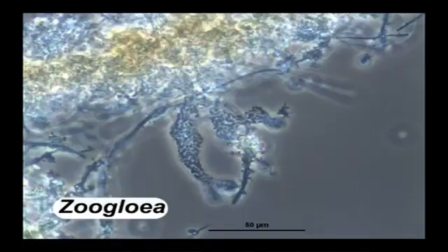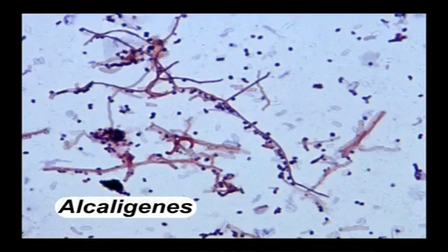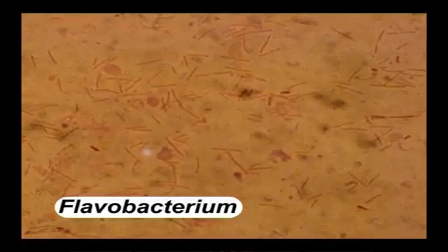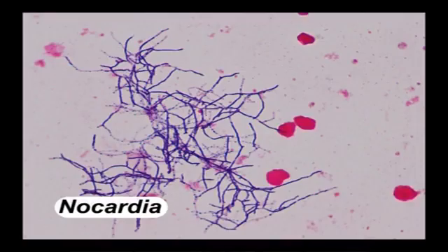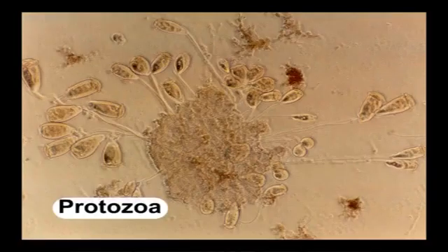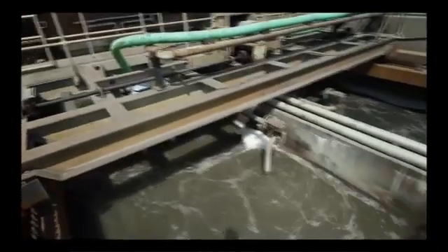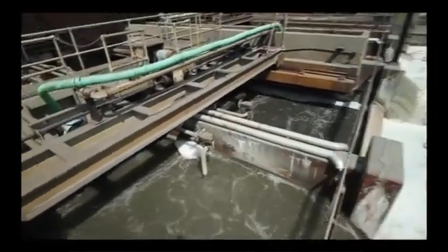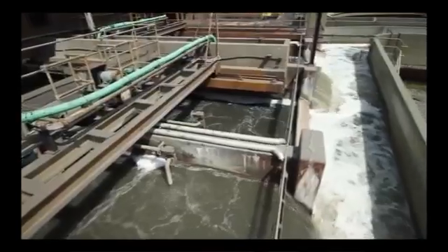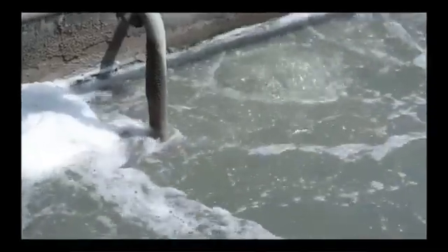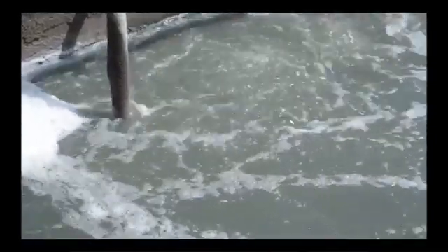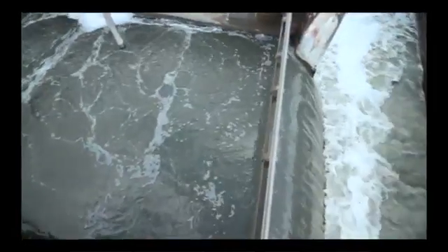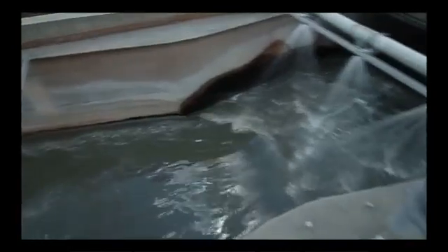processes. Typical microorganisms present in trickling filters are Zoogloea, Pseudomonas, Alcaligenes, Flavobacterium, Streptomyces, Nocardia, fungi and protozoa. The crux of the process is that the organic contents of the effluents are degraded by these attached growing populations, which absorb the organic contents from the surrounding water film. Oxygen from the air diffuses through this liquid film and enters the biomass.